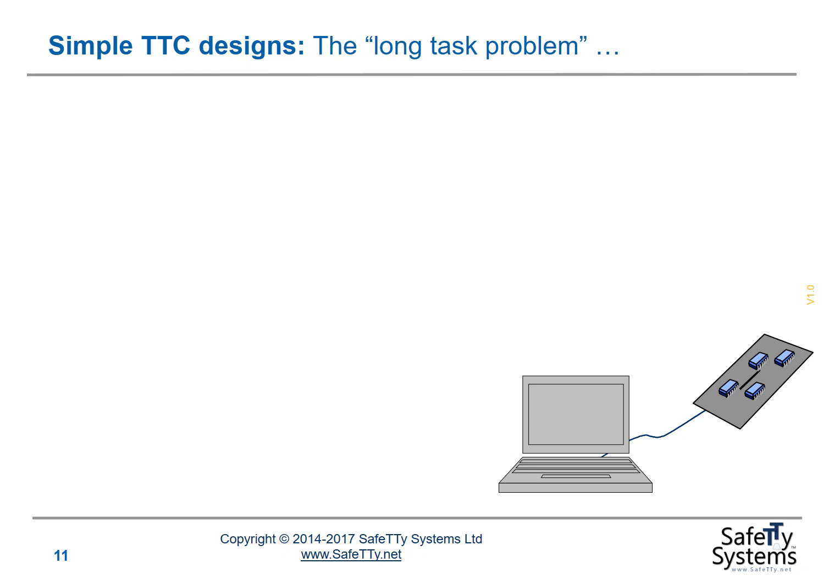Suppose I've got an embedded board and I want to send some information. I'm going to assume I'm using a serial link with an RS-232 type connection and probably some kind of USB to serial converter in the link, but I'm going to use a UART connection on my embedded board and send a string of characters to my laptop.